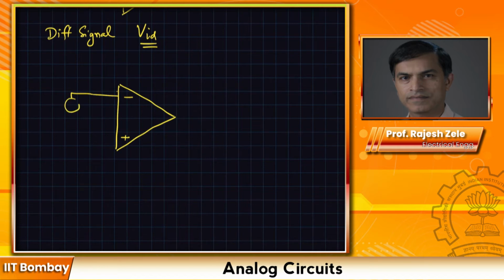Then I'm going to break that voltage source in two pieces first. And I'm going to make this VID by 2, and this is also VID by 2. So same thing, right? You can say apply plus minus plus minus. I just broke that voltage source in two pieces with VID by 2, and this center point is my common mode potential for the amplifier. So here I can put in something called, let's call it VICM, plus minus.